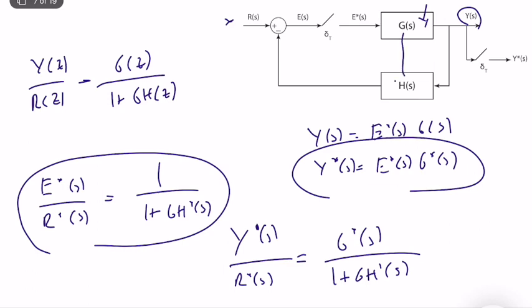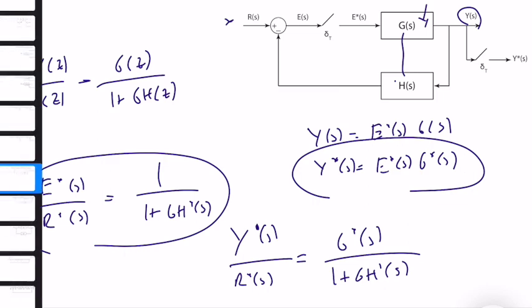which is a transfer function such as A of s, take the inverse Laplace, compute a of t, sample it a of k, and compute A of z, which is equal to GH of z. It's kind of indirect, or it may not be very intuitive at the beginning of the course, but you will get used to this kind of difference from what we learned from feedback systems and signal systems courses. Okay, that's great. So now let's solve a simpler one.